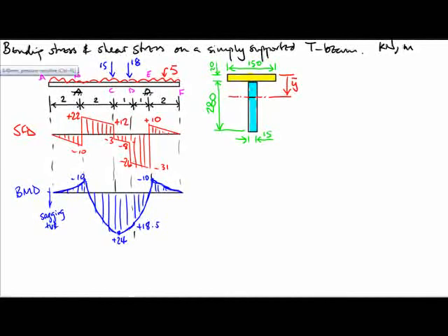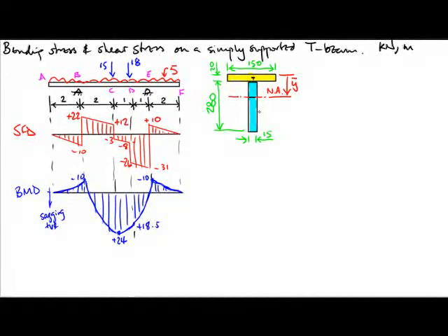To get the second moment of area, we need to firstly find the centroidal axis of this overall section. It's not too difficult to find the centroid of the individual blocks, and they are just halfway up the rectangular blocks, but what we actually need is the centroidal axis for the overall cross section,